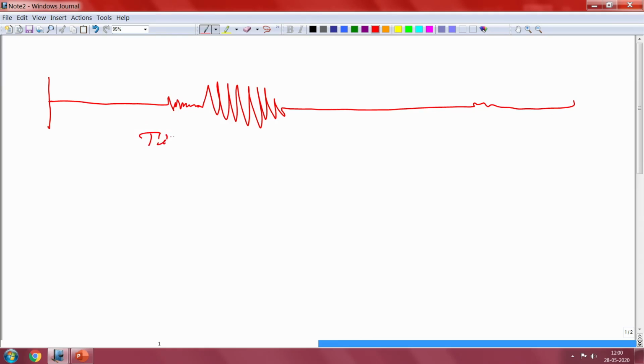So, this is the typical record. This will be the acceleration or velocity component. You can see generally the peak occurs on the S wave portion. This is what we call the peak. Generally, this portion of the data will be looked at very closely by engineers, and they will use this for the design, as we have seen in the wave propagation theory.